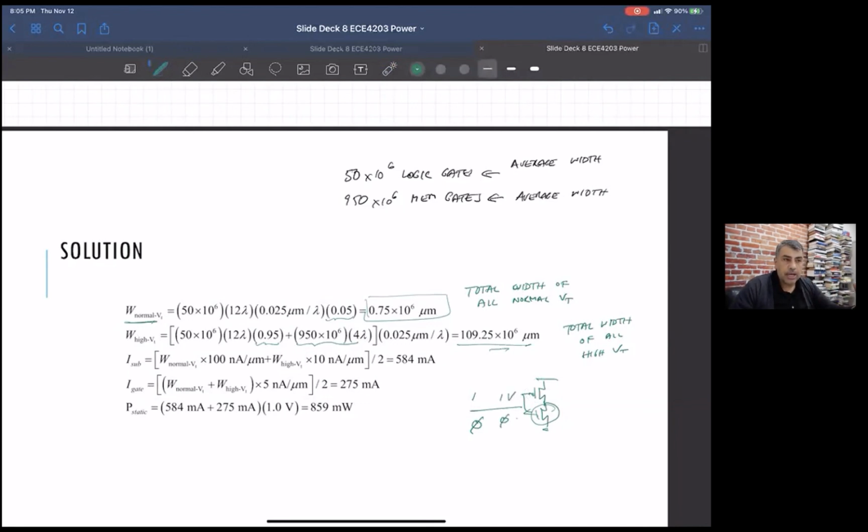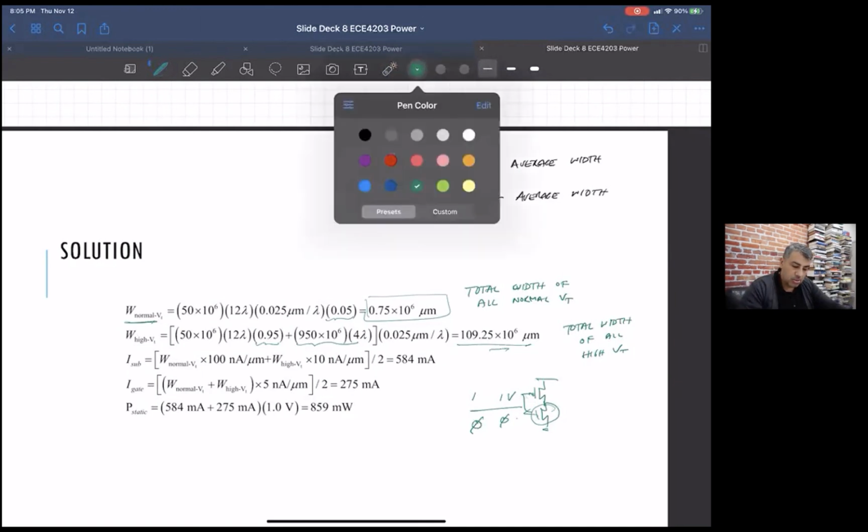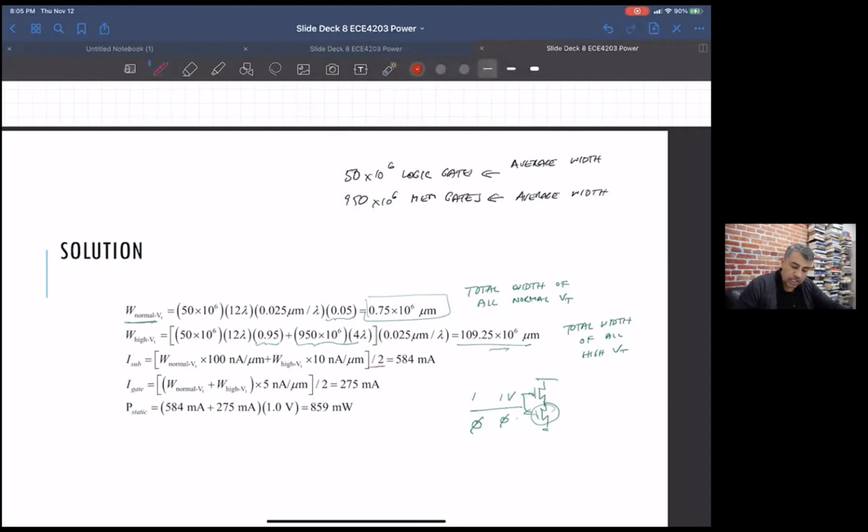So the way to think about it is, on average, only half the transistors are in a situation where their leakage mattered, because the other half are supposed to be on anyway, right? Because even if you're not switching, you left your CMOS gate in some known state. One of them is on and the other one is leaking away. So that's why you do this rule of thumb where, after the end of everything, you divide these leakages by a factor of 2.